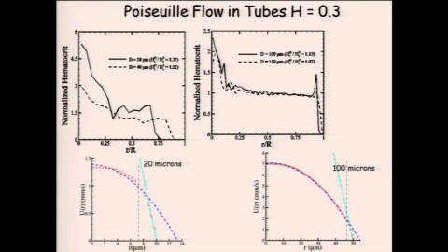For the larger tubes of this series, we went from about 10 microns to 150. And you do get a flat portion, but you still get a peak in the middle. And of course, you have a layer near the wall called the cell-free layer where there's nothing in both cases. And that cell-free layer seems to grow as you get to smaller tubes, although ultimately, when you get down to capillary size, the cells rub up against the wall, so this idea loses force.